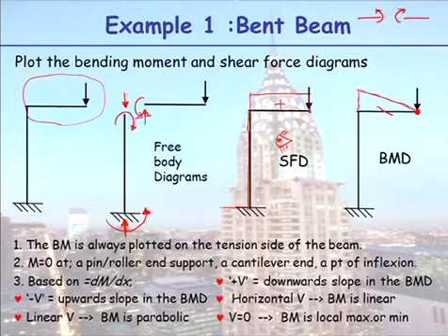Now when we do go around a corner, we usually just close it up, but you don't have to. You draw the line down. Now coming back here, I've drawn my bending moment above. Can you imagine how this thing deflects? It's very important that you can imagine. This thing would deflect down like so.